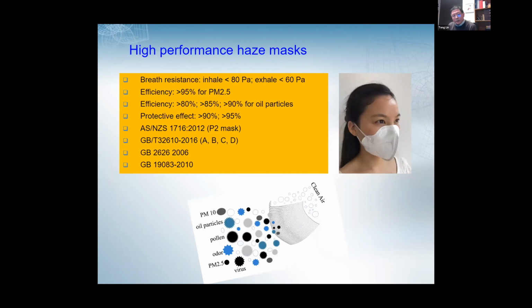With the nanofiber produced, we found it's useful for many applications. Our first product is a face mask. We found if we combine this nanofiber mat with the melt blown, we are able to produce a nano face mask with a very high efficiency, but the pressure drop is low. For this face mask, the resistance is about 80 Pa, so that the mask doesn't need to have a valve, but breathes very smoothly.